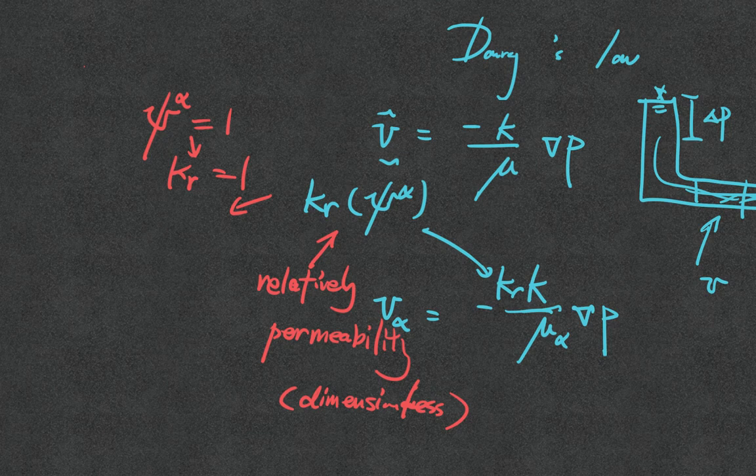Solving the problem is much harder if you try to build the boundary value problem. So far so good. Any questions about the theory of three-phase porous media? How many of you want to do a final project on three-phase material? No one. It would be good to always challenge yourself if you like. But remember that there's no linear counterpart for that, unless you assume a linear retention curve, which in that case won't be very practical.